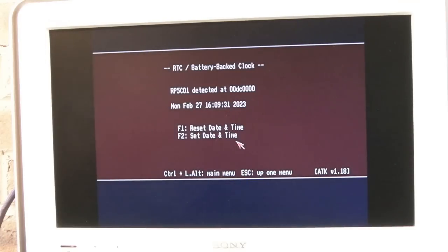I was able to fit that in the ultrasonic, so the audio sections got a really thorough clean, including the connectors, and it looks so much better. But obviously there's some exposed copper, that's all that's wrong with that. I've just set the time and date after fixing the real-time clock area yesterday. You know what, it just works. I'm amazed I haven't had to do any tinkering with that, and after cleaning out that little yellow trim cap there, it works, as you can see. But yeah, the real-time clock has survived that corrosion.